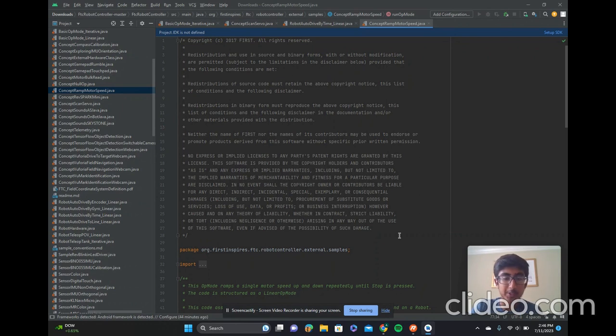In the configuration, you would either have a configuration or you have to create a new configuration. So as you can see, there's available configurations. You can press edit, and here there's the options of a control hub portal and the webcam. So you want to click on the control hub portal, click through the control hub, click on motors, and if you see here, I've already preset the motor into this.